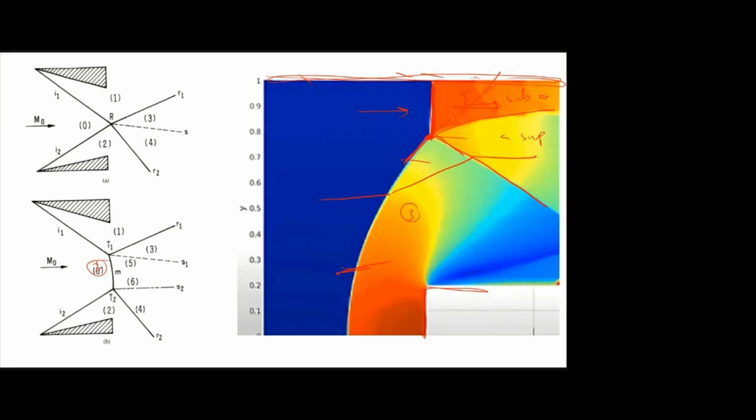This is another example, and here the third example. So this is normal reflection. If the Mach number is very high, there will be a normal interaction. Then this is the refracted wave. But if the Mach number is less, then it cannot produce a strong oblique shock wave up to this point. So this creates the Mach wave in between, normal shock wave in between these two.